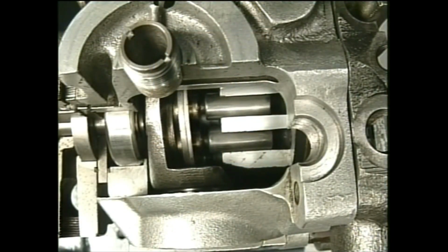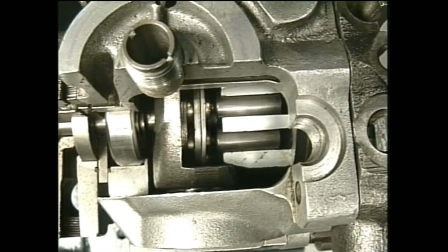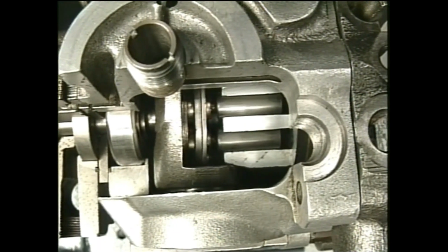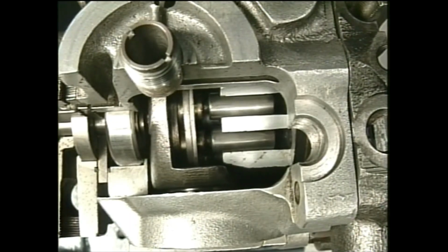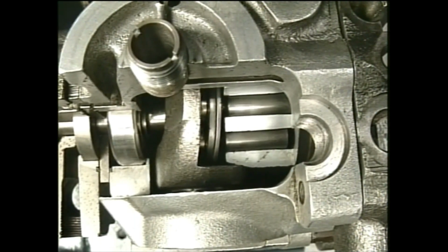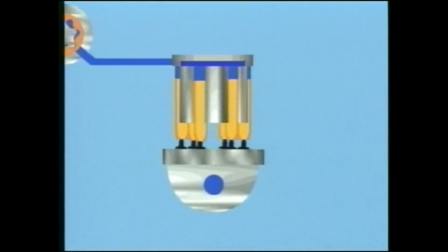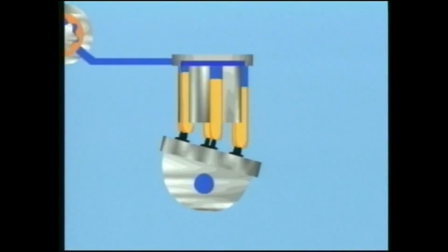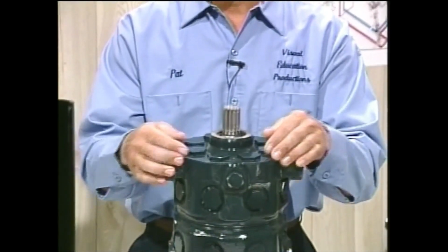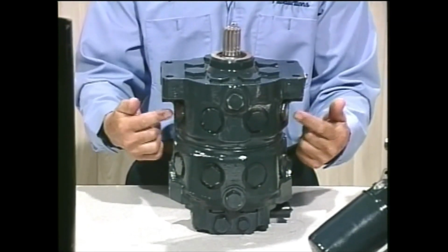The axial piston pump varies its volume by adjusting the length of its stroke. This is done by reducing the angle of the swash plate the pistons slide on. As the angle decreases, the volume of oil pumped decreases. And as the angle of the swash plate increases, the volume pumped increases. There are several variations of the radial piston pump, but we will illustrate only one pump design. The radial piston pump has cylinders that point away from the center like a starburst.